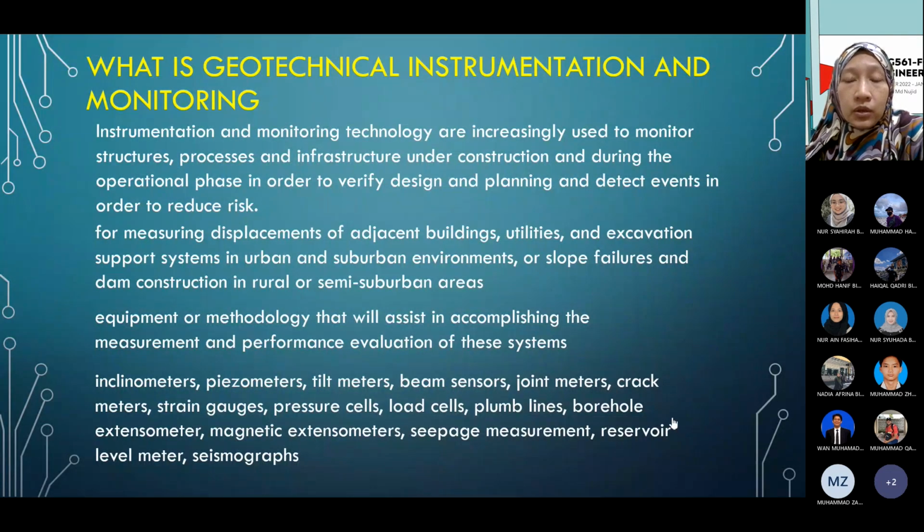So if you do not carry out any measurements on the groundwater table, by simple assumptions, for example, that there is no groundwater table effect on the bearing capacity failure or anything related to your design, that will bring a future failure for the foundations.